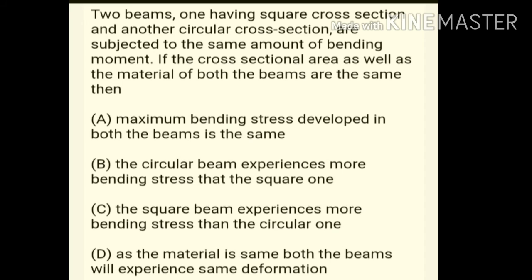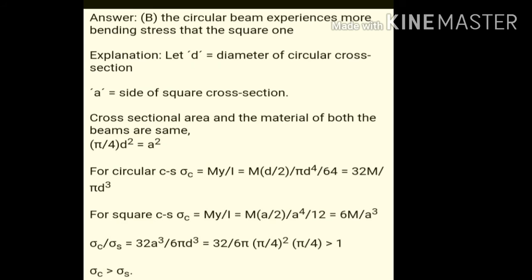So in this case again we have to use the bending stress formula. We know that the standard bending equation is M by I is equal to F by Y is equal to E by R. This you have to remember. So we have to substitute and identify which is getting more stressed. Here the stress is taken as sigma C, the notation is just a stress notation, sigma C or F whatever.